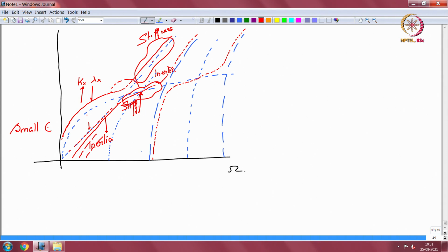Okay. Less and less stiffness, the wave number rises, kx goes up and lambda x comes down, so that wave speed goes down. And high stiffness, you approach the plane wave closer and closer. At almost infinite stiffness, you reach the plane wave back.